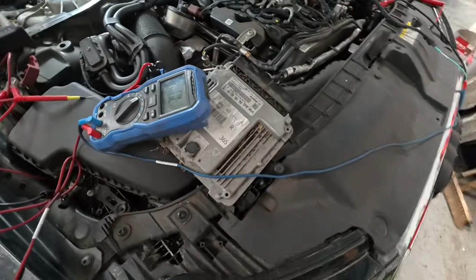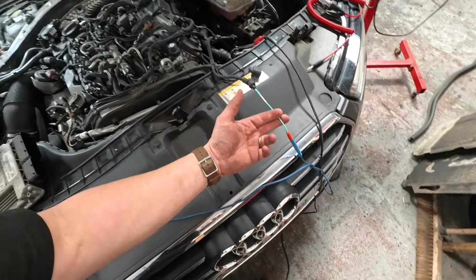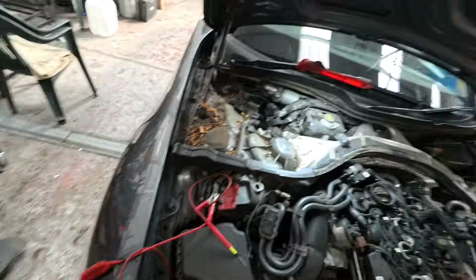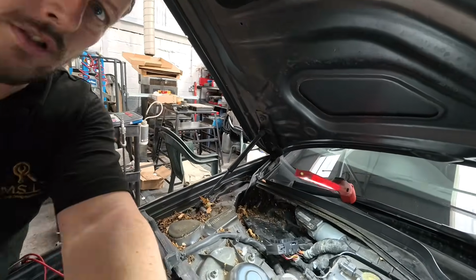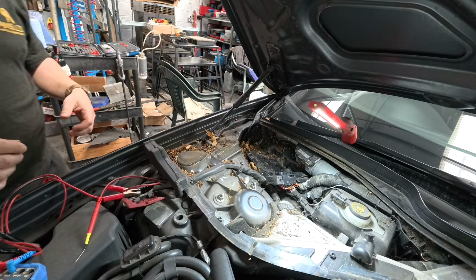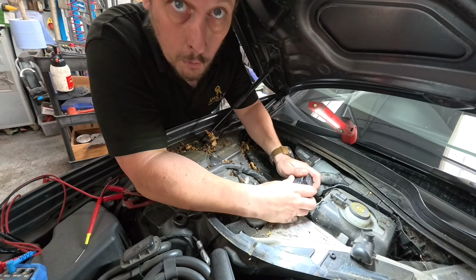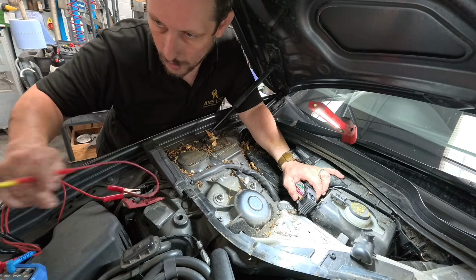I pulled the engine computer out, and I've run that. So that's into the control wire. That's coming up here. Let's set you up on there so you can see what's going on down here. Now, using E3, we can tell exactly which pin output it is on the ECU. It says B3. There's a grey and white wire.